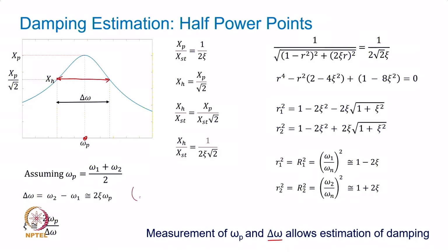Suppose I have a vehicle chassis which is being tested for its overall structural damping. People do testing on the chassis, body in white test, they call it. Now, there you do not have any excitation mechanism. So, the typical way in which such systems are excited is using large electrodynamic or many times hydraulic or pneumatic shakers.